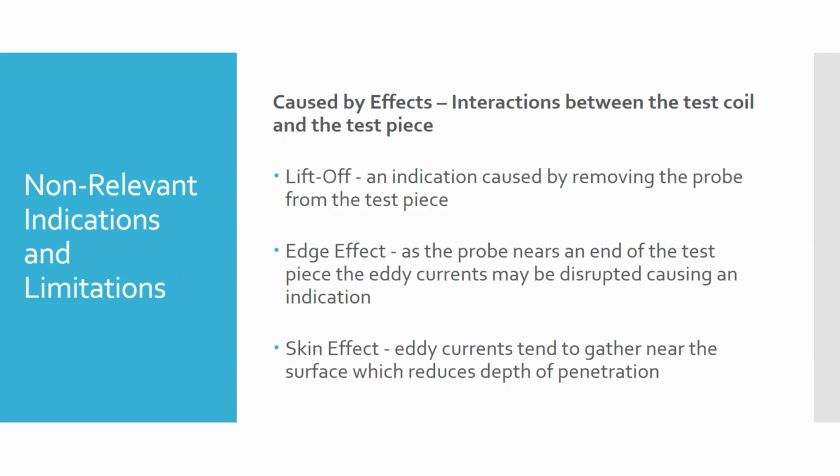So that's where that balance comes in. Okay? And that's where the multi-frequency probes come in, where it can swap back and forth between a high frequency and a low frequency. Or like that array probe that we saw the video of, where it would run different combinations of coils, different size coils, different frequencies, and it could map front side features and back side features and everything in between.